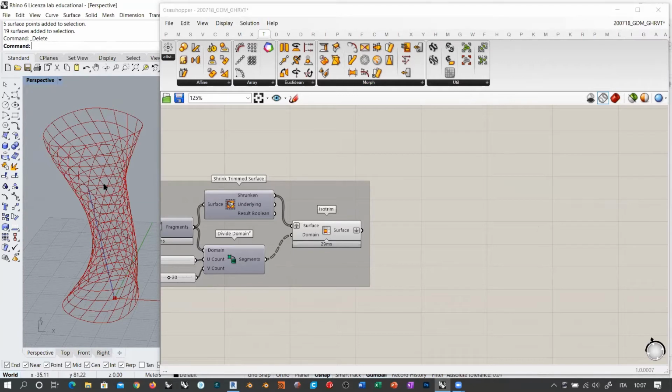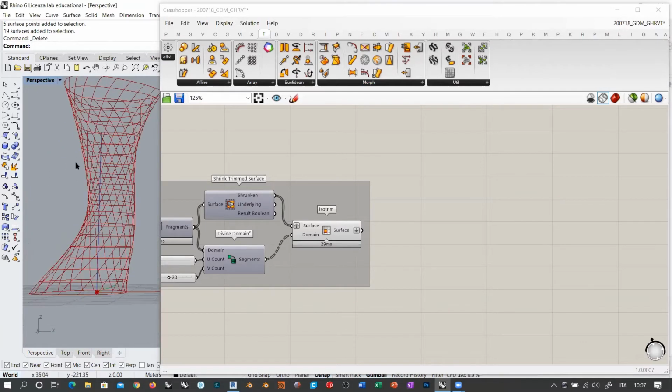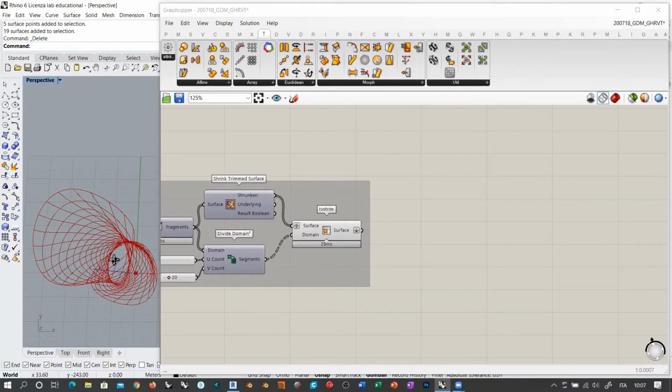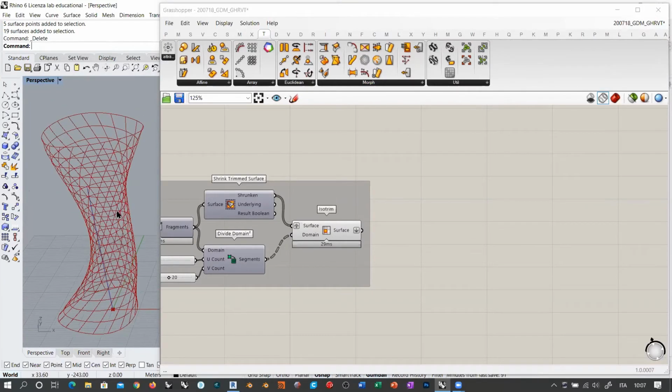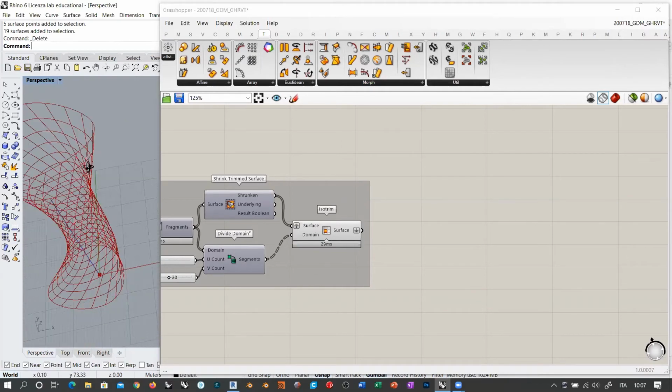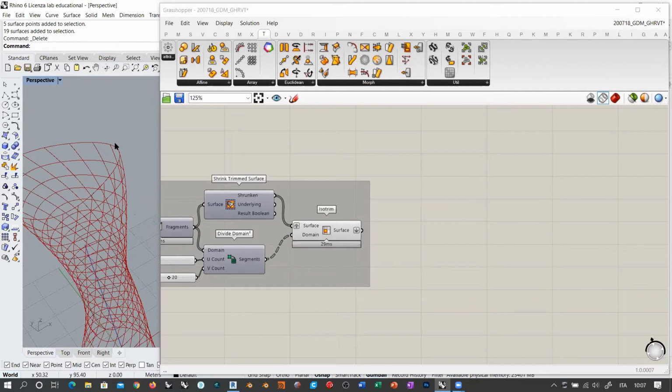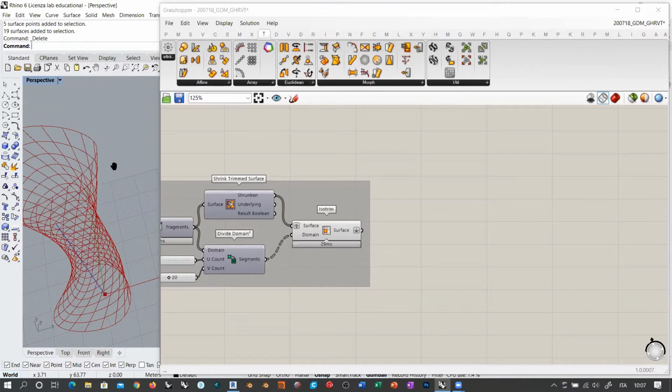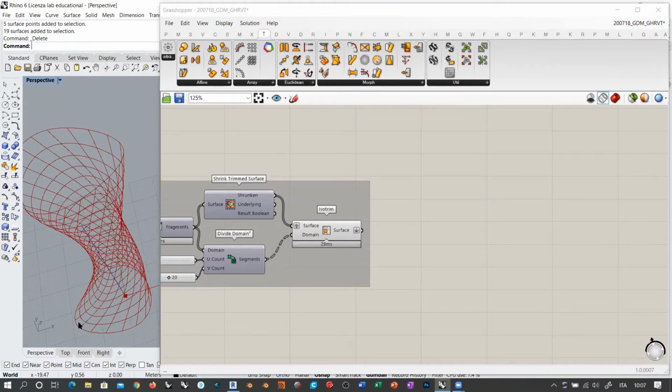Not because we cannot send non-planar geometry to Revit, but thinking about production eventually, you might want to work with more planar shapes. This kind of geometry is the worst scenario that you can have, because this twisted tower is like a deformed cylinder, and there are some areas with a huge curvature value, like this one, for example. And also this one here at the base.